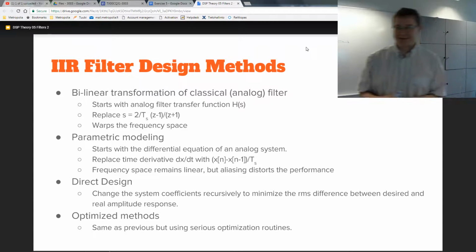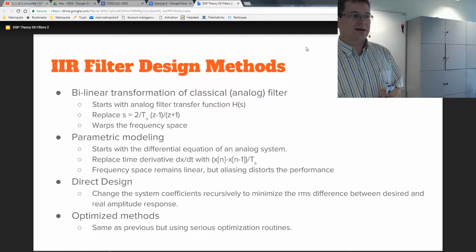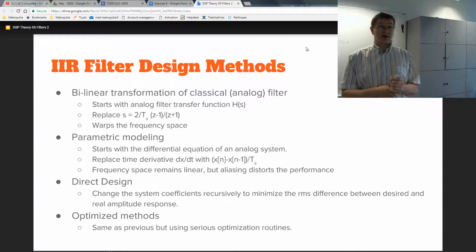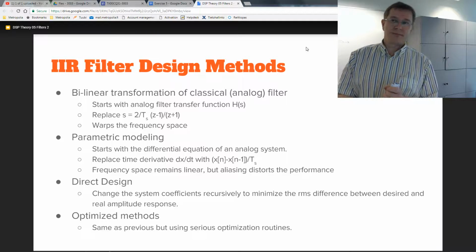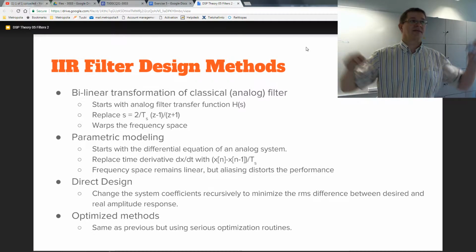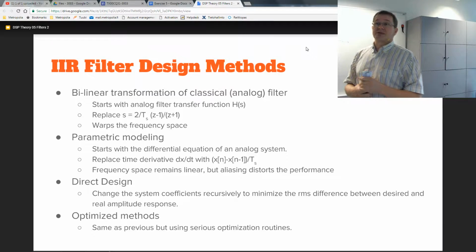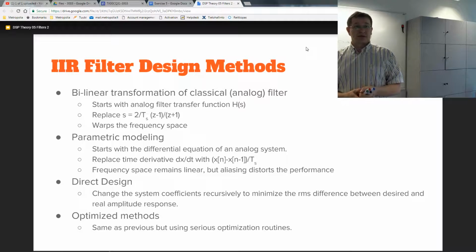There are some analog filters based on negative feedback and Sallen-Key structures on operational amplifier circuits, and there you can sample the system. Where you have an analog system, you can always make a model of it, and bilinear transformation is one method of making such a transformation.